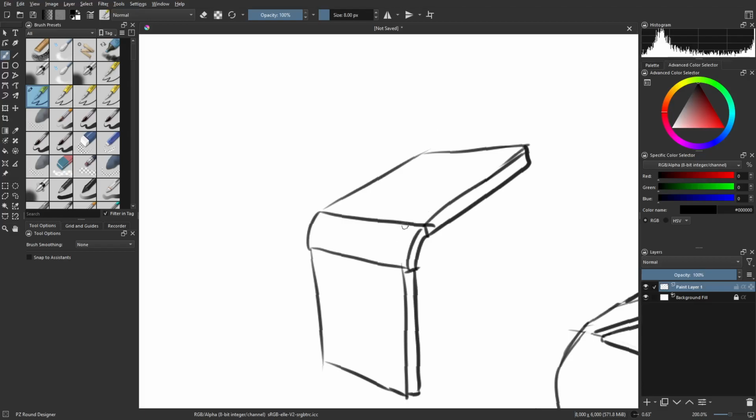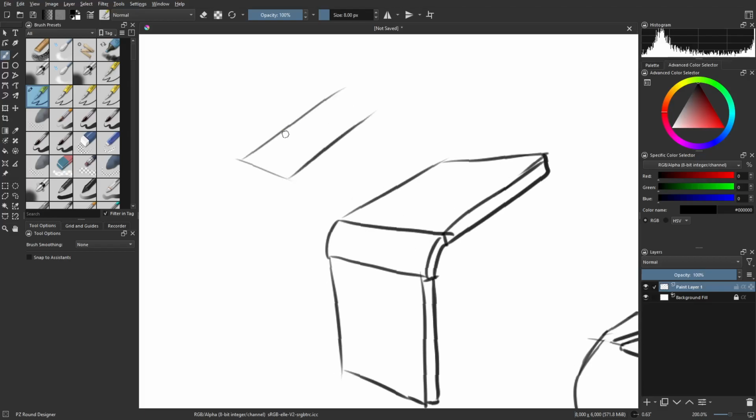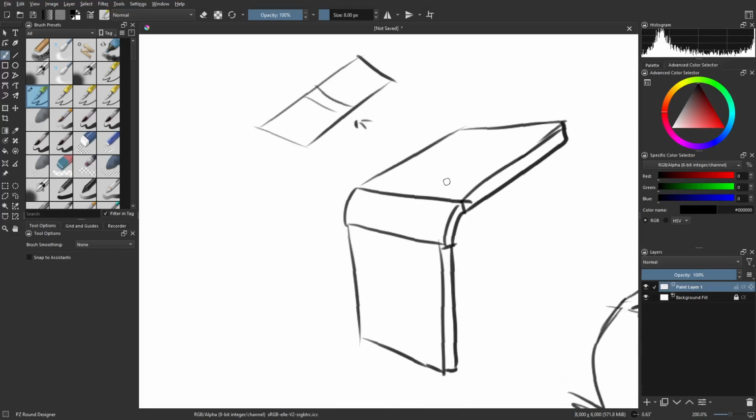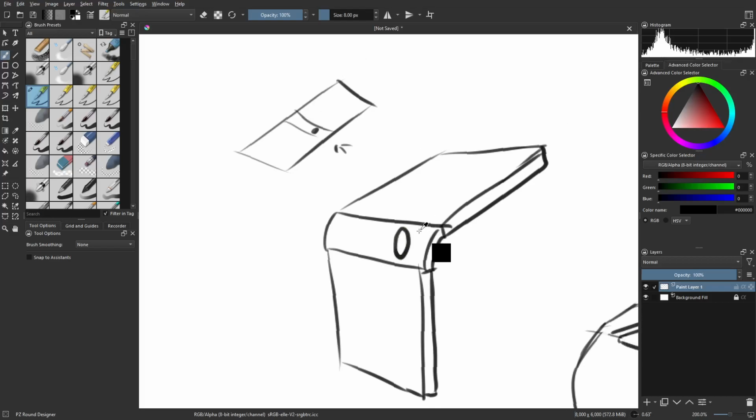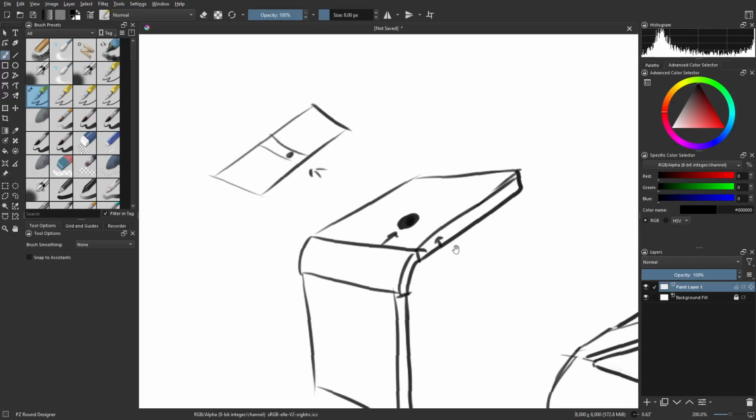But if you're going to bend a shape like this, where it starts flat, and our bend would take place here, right? And then you start bending it, you can't put a circle there because what ends up happening is if it was existing here when it was flat and it bends, it's going to create like an elliptoid. And that's not going to be proper. That's not something they want to do. So there's actually a distance that must be traveled backwards until that will maintain its actual shape there, and it's dependent on the depth of the metal.